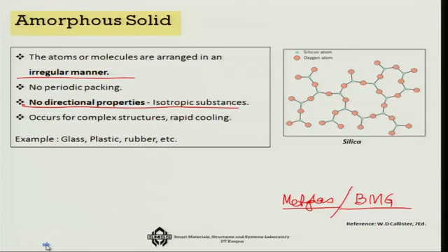Of course, the other thing, which we will talk about at a later stage, is the polymeric chains. Polymers are by nature amorphous, because depending on what is coming in the cross chains of a polymer, it may never actually show a long range order. So, there are some materials which are by nature amorphous, and there are some materials which are by nature crystalline, but you can force them to take an amorphous structure. For example, the bulk metallic glass or the metallic glasses.